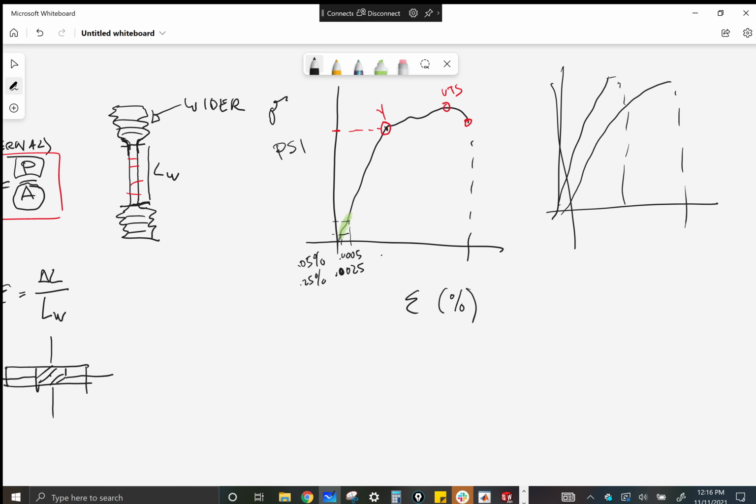Ductile would be more like this one, where it has a large plastic region. So in structures, you can call assemblies brittle or ductile too. In earthquake regions, you make ductile assemblies so that they can move around. Maybe they're damaged, but they won't fail catastrophically really quickly.